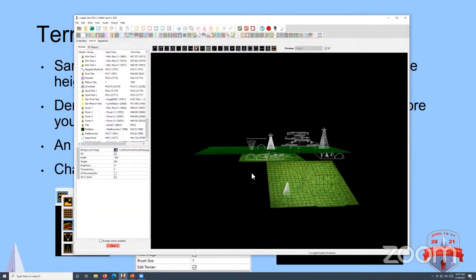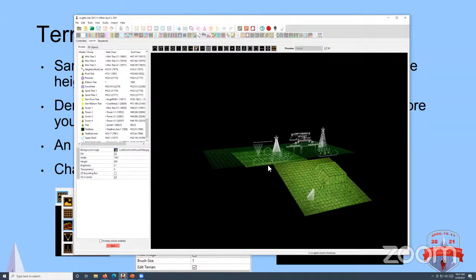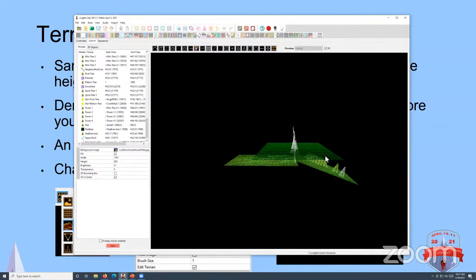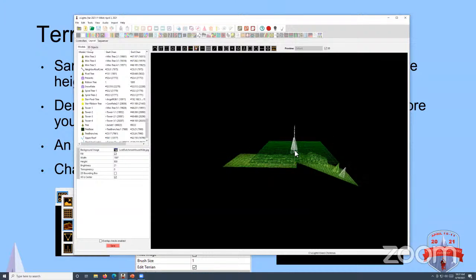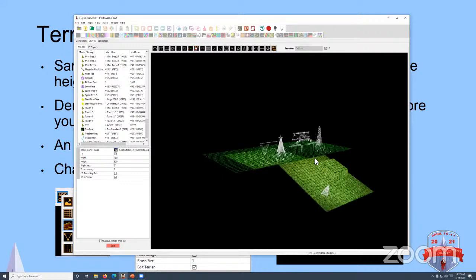Yeah, what can get tricky is if you're rendering from a left side, it depends on what models you're dropping it on. If you really only wanted to render to the models on that side, you'd have to have a group that only has those models. If you render to everything in your display from that angle, then anything along the plane that you're rendering is going to be the same color all the way down.